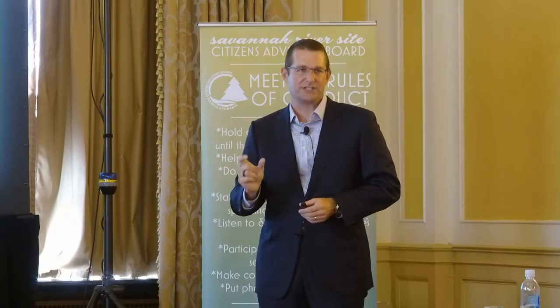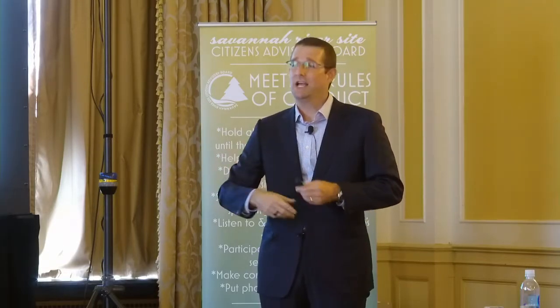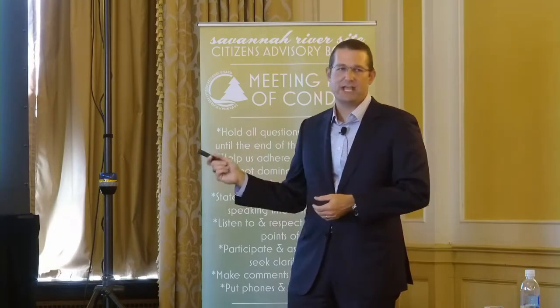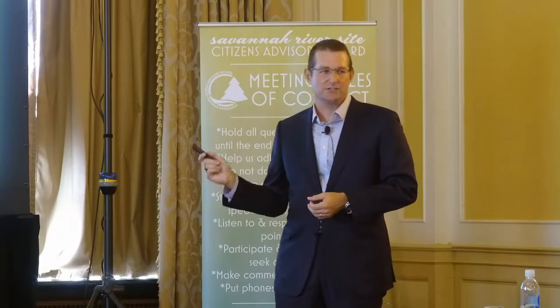The area that we're concerned about is an area where we have unwetted solids. And the best I could come up with is, because I have young kids and they drink a lot of chocolate milk, they throw the Nestle's packet into the milk, and some of it incorporates right away, and some of it doesn't and balls up on the top. Those are unwetted solids. And of course, the kids have to stir them for a while to get them incorporated. We have that same thing happen in here. When those solids are unwetted, they are highly abrasive.